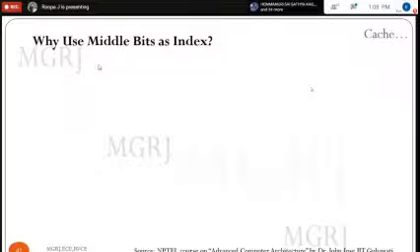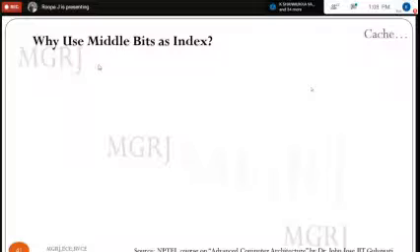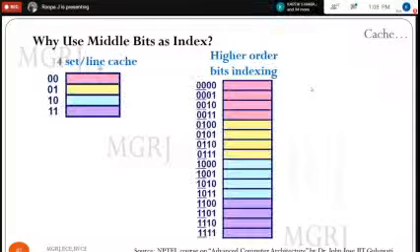Now, there is one point we are supposed to understand. Please keep in mind, whether we are using direct mapping, set associative or fully associative, your CPU or your processor sends only the physical address, right? So while bringing the physical address, we are supposed to check in what way we index. You know that the entire cache has a block index, a set index, and tag bits, right? So when we are indexing, what sort of addressing will we use? Just listen here.